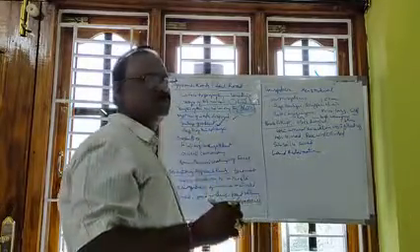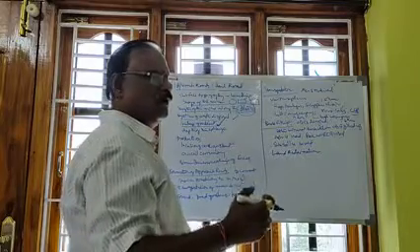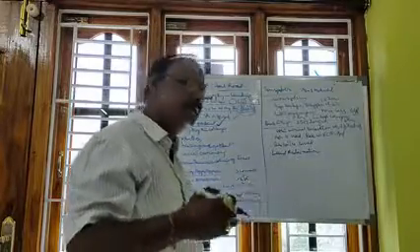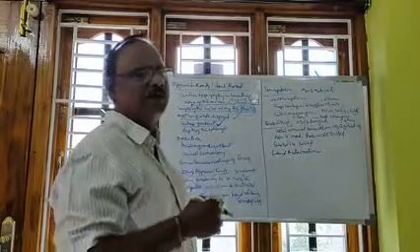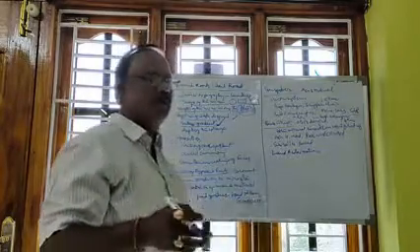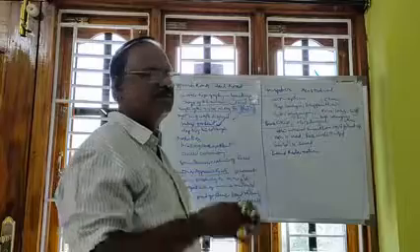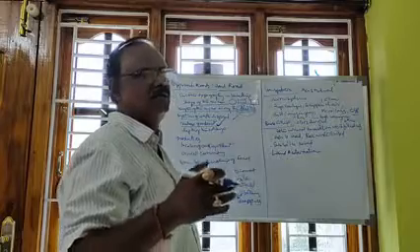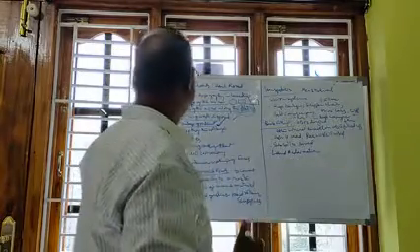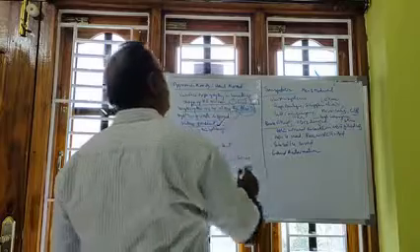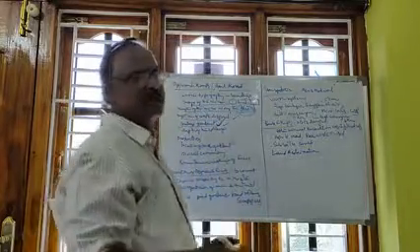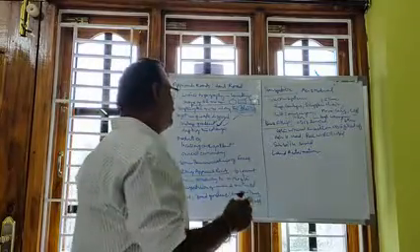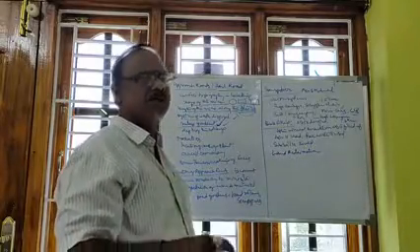So the haul gradient is the approach gradient, where the dumpers are used for transporting. Where a conveyor is laid out along the approach road, it must also have a certain gradient. If the gradient is high, the material cannot be transferred, because it falls due to gravity. Whether a conveyor or dumpers are used for transporting the material, the gradient must be negotiable, not very high.